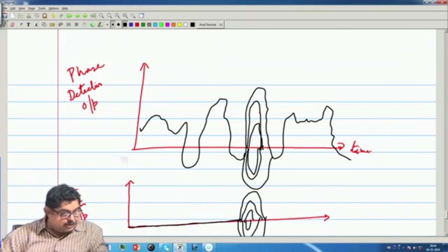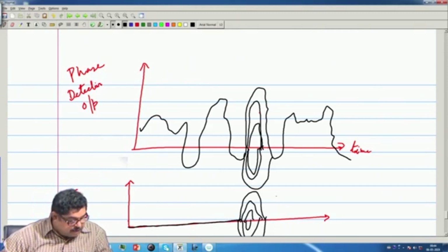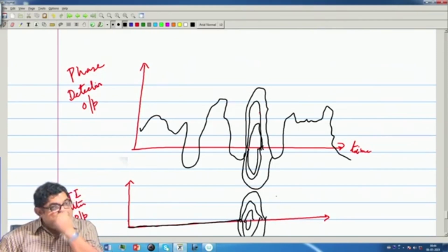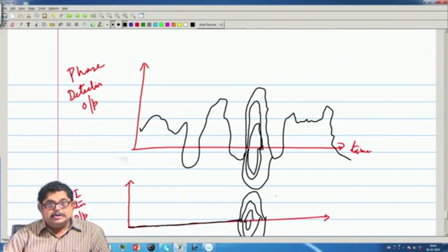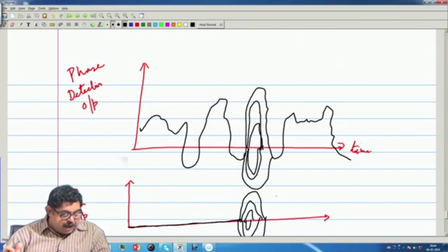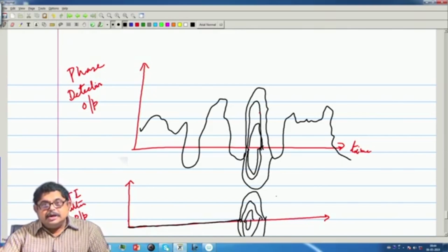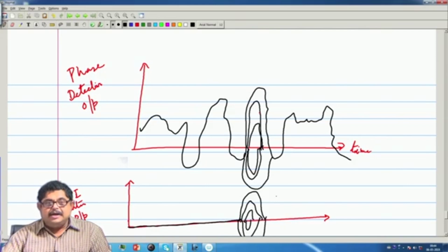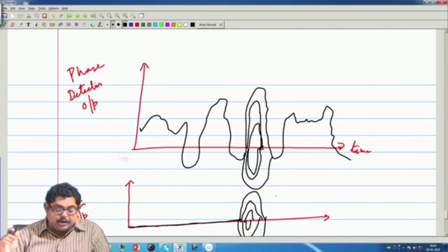So, you will see that this thing will be there, you will be able to understand that this is a moving target. Now, generally the signals are bipolar, because phase can be in both ways. So, that is why generally if you put it to an average voltage indicator, it will be 0. So, generally this bipolar signal MTI filter output is given to a rectifier and then to the display, which shows that there is a target.